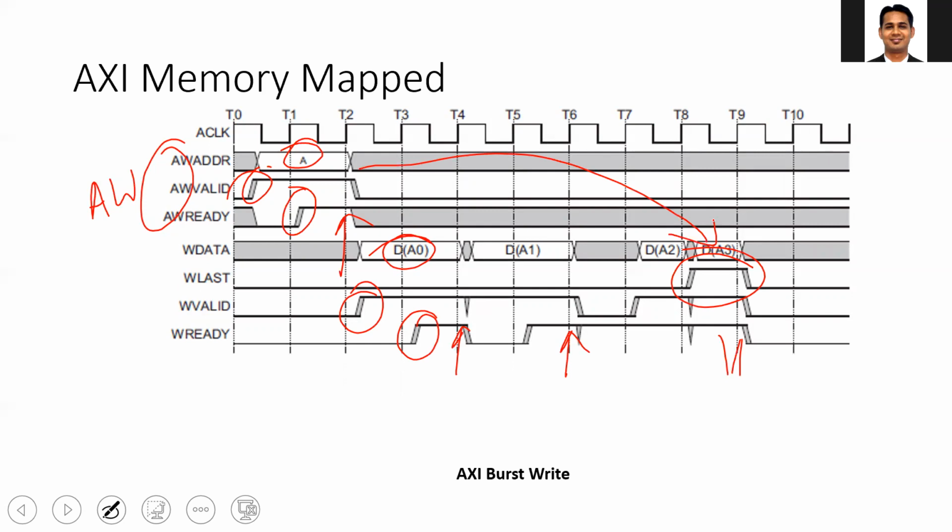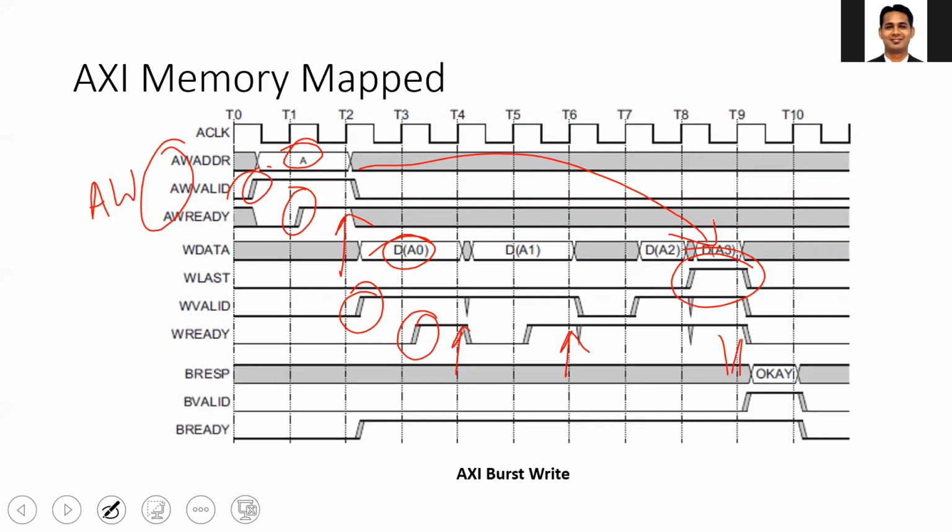Then the slave takes the data, performs the write transaction, and replies over the write response channel by putting the information whether the write transaction is okay or not okay, with the corresponding valid signal. The master is ready, the master accepts, and here your write transaction is complete. So in the case of the write transaction, the information source puts the address and control and data information, and the information destination will give back the outcome of the transaction.